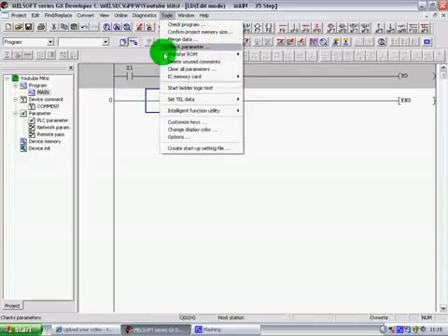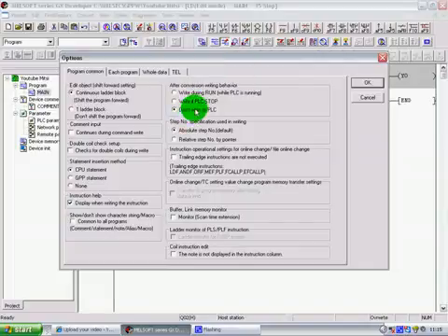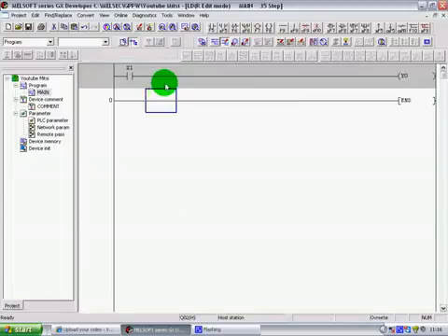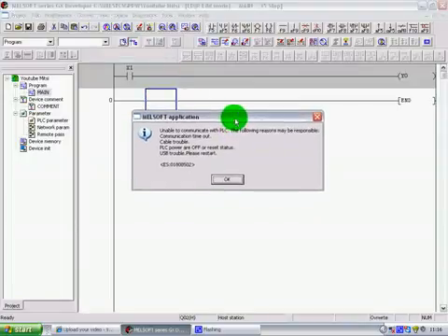This is where I showed you that it's very important at this point, if you're not connected to your PLC, that you have this done here, because if we have any of the others and I press F4 to convert, it comes up with a communications error. It's shown us that we're not connected to the PLC and it can't write to the PLC.